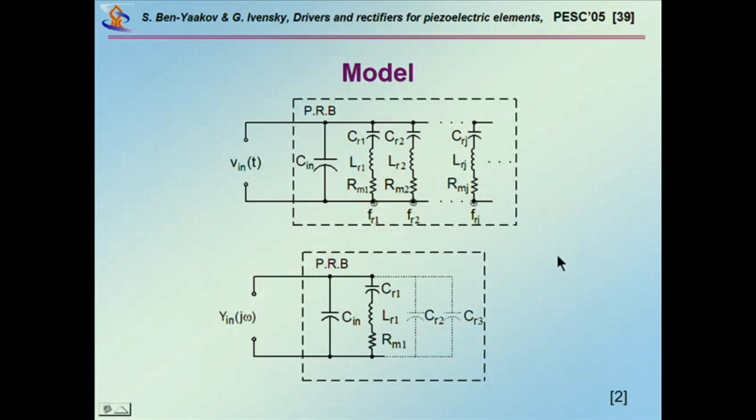If I look at the piezo element, in which there is, again, this dielectric capacitance and all the other modes, then if you work at the first, or lowest, resonant frequency, all the others are below resonance, so they are capacitive. So there is some capacitive addition here, and in fact, if you measure the capacitance at low frequency, you measure all these capacitances. I'll show you this a little bit later when we talk about how to extract the model.